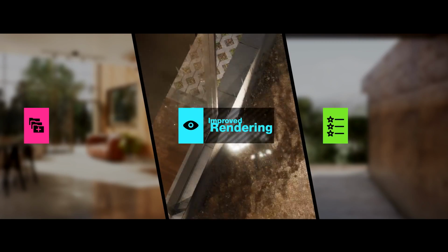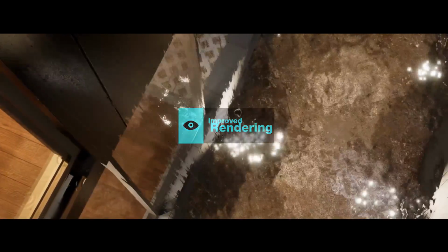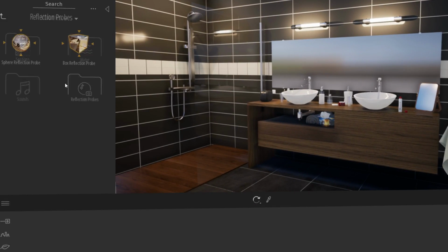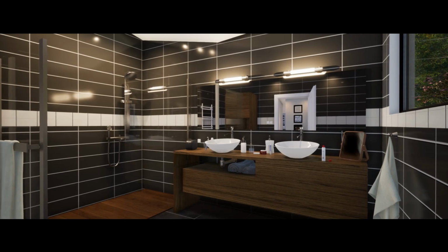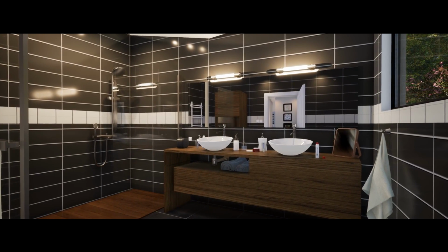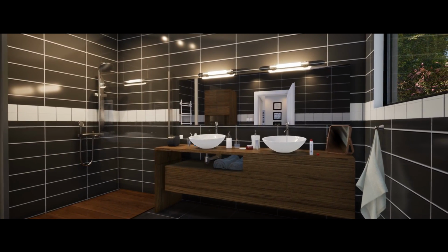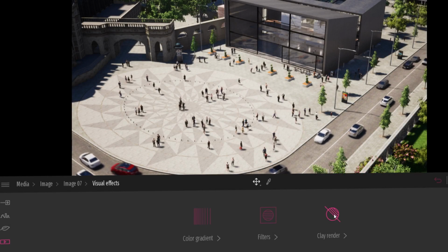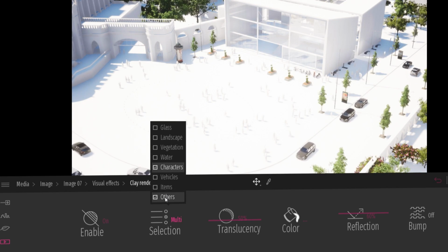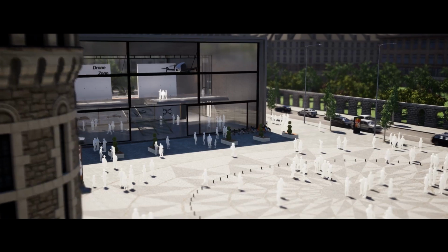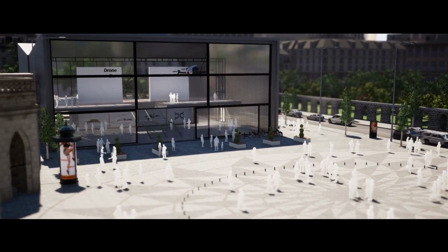For example, in most BIM projects, there is the toilet and all the tubes where the water flows. Sorry, I forget the word. But all those types of items that are always hidden from the project, you don't see them if you want to create a VR experience. So remove all those assets, optimize your file. Then everything that you are adding in Twinmotion is already also optimized. So if you are adding, for example, one tree and you duplicate this tree, it will not take more performance. Only one tree will be called in the back.